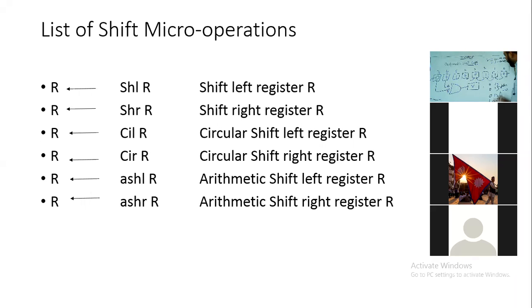You just remember if both inputs to the XOR gate are the same, the output is 0. The output will be 0. If both bits to the XOR gate are different, if it is 1 0 or 0 1, the output of the XOR gate will be 1.